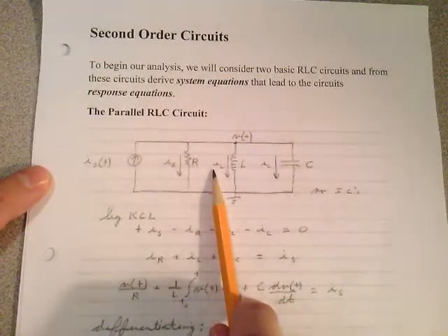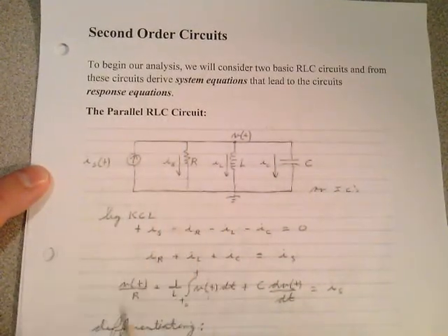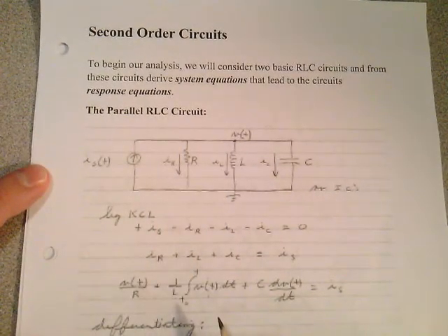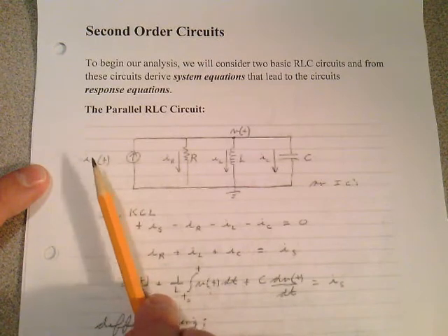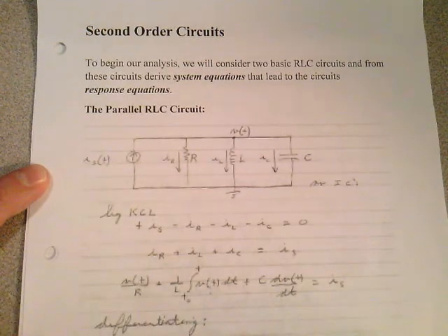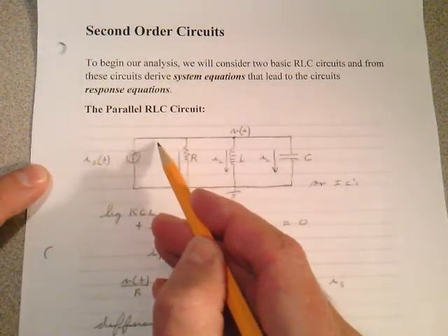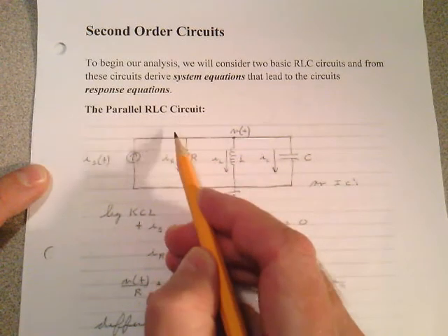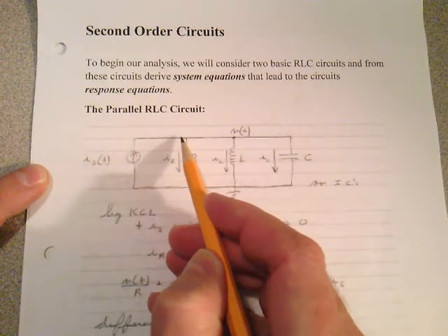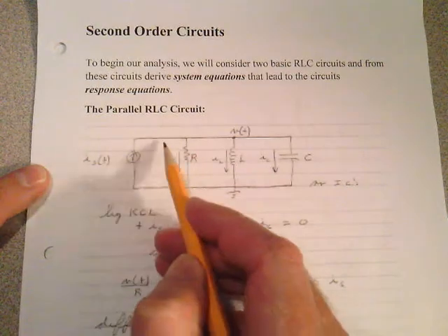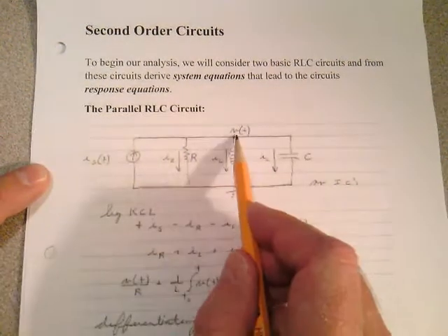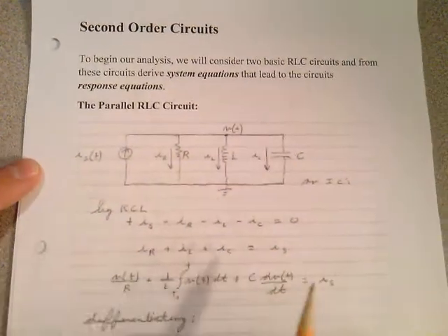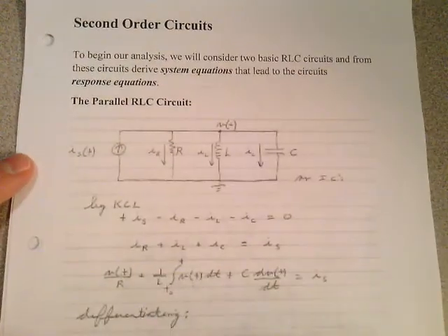We're going to start by looking at a parallel RLC circuit that looks like this. Now, on our responses right here, we're only going to deal with step responses. In other words, step responses in current or step responses in voltages, where we're basically just throwing a switch up here. So you can see this value is going to go from 0 to IS as a step response. We're going to see what it does to the voltage at this node right here, keeping in mind there are no initial conditions here.